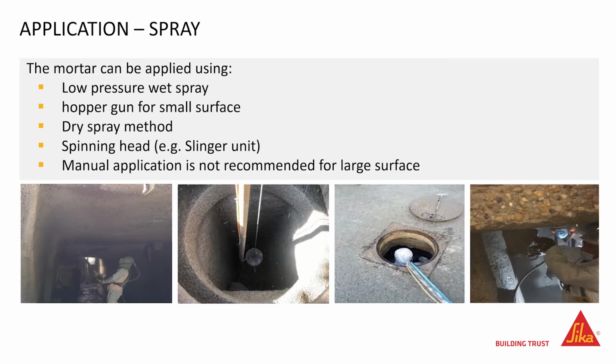Now let's have a look at the different application techniques. The mortar can be applied using a low pressure wet spray, a hopper gun for small surfaces, the dry spray method, a spinning head, e.g. slinger unit. Manual application is not recommended for large surfaces.